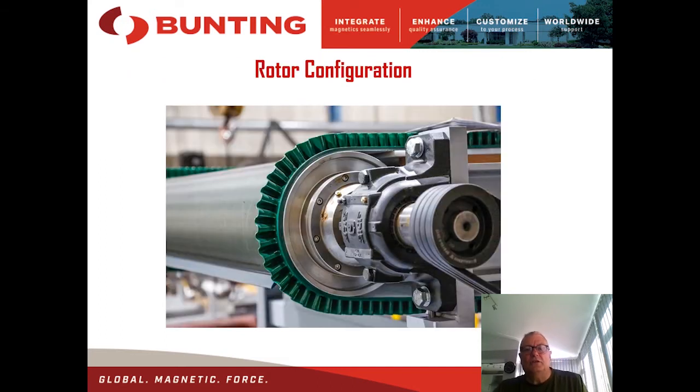This is just a close-up of the front pulley system, belt drive pulley here, and the bearing system here. We have an internal rotor and the external carbon fiber shell here on that pulley, and then we have our belt system here, which is a hard wearing rubber type belt with guides here to keep material in the influence of the eddy current field.